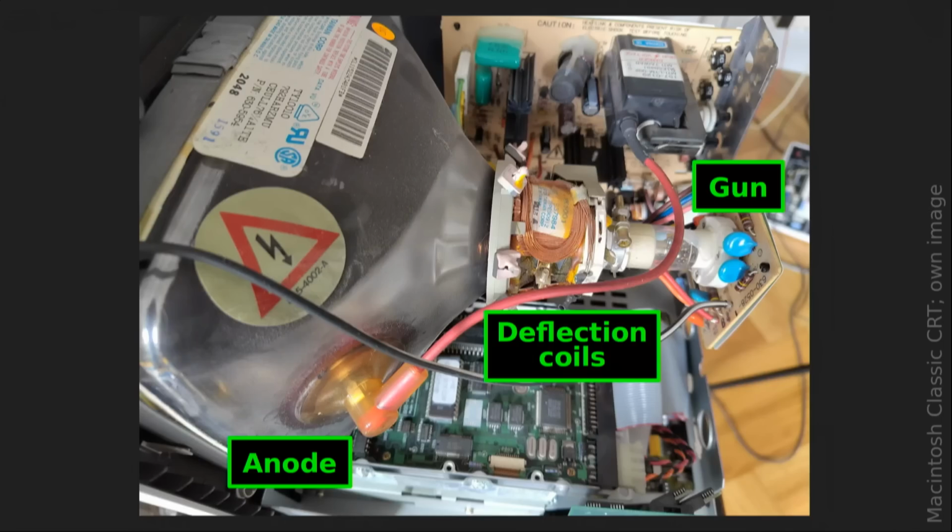Then so-called secondary electrons stagger to one of the tube envelope anodes. Negative charge moves from the anode to the cathode. Current flows through the tube. And finally, though they're not shown in this diagram, you'd surround part of the CRT, usually the base of the bell, with electromagnets. This is how you deflect that electron beam so that it lights up the part of the phosphor screen that you want to light up.